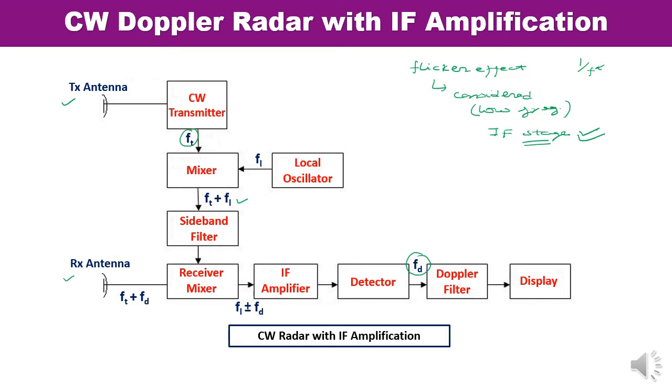The problem of isolation is the main determining factor, as a consequence of the continuous wave power from such a radar, which sometimes exceeds 100 watts and sometimes is very much less. Gunn diodes and impatt diodes are used, and for the highest power continuous wave, magnetrons are also used as power oscillators in the transmitters. So you must remember which devices can be used.